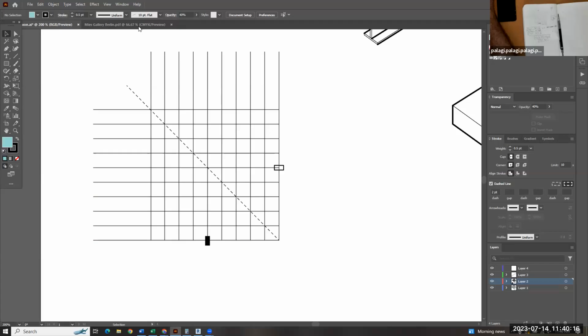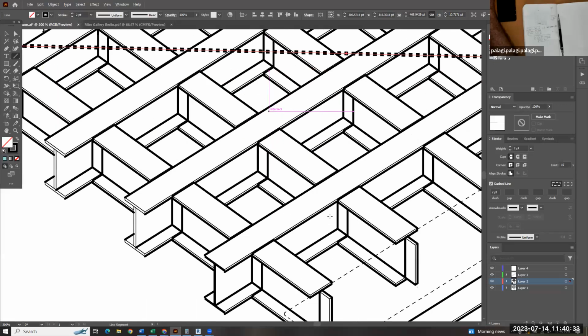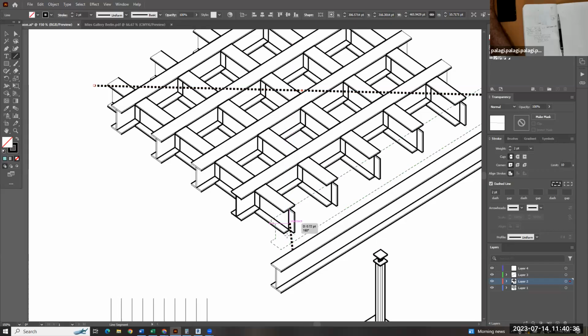to diagram. Because we've done this, you could actually do a quick little assessment. If we were to draw a line across here and somehow show that this is the trib area, we could say, what is the trib area? You could have a different basic load dropping from each one of these coming down onto this, because that's what's actually happening, right? That's just figuring out what the trib area is for this one. Well, it's there to there, there to there. What's that square footage?